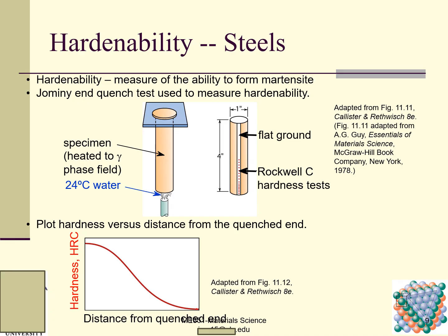Regarding hardness testing, we have four different hardness testing methods. One is Rockwell, and the second is Brinell. HB means Brinell, HR means Rockwell, and we have Knoop and Vickers. Knoop and Vickers are designed specifically for micro hardness testing, and this is a bigger scale hardness testing. Mainly we use Rockwell or Brinell hardness testing.